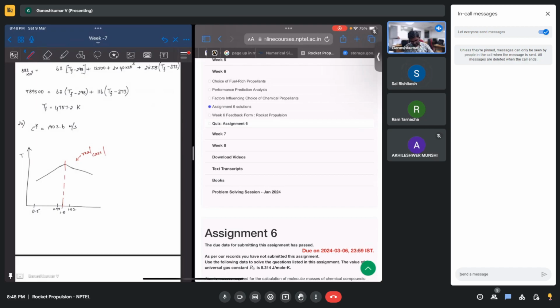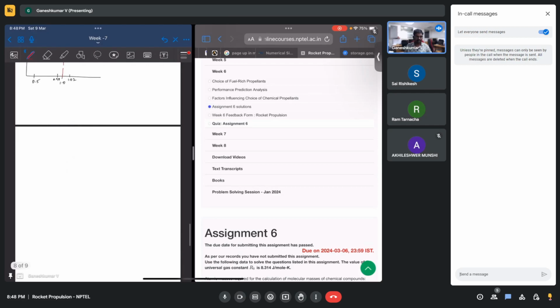The only thing I'm trying to say is, you are trying to find the divergence losses, right? The divergence loss is going to be mass flow rate times the velocity. The mass flow rate will have a cos alpha by 2 and the velocity also will have a factor. So what is really the force you are getting along the actual direction, you calculate that, and then the total force you subtract, that will be your divergence loss.